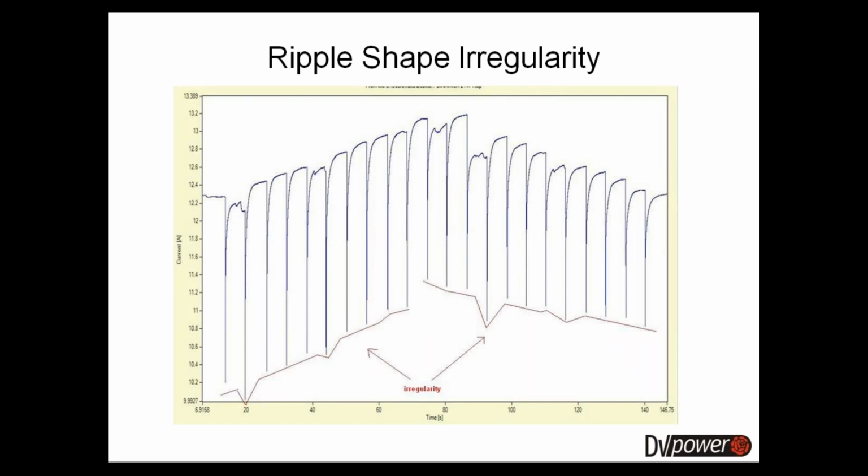However, when the tap changer has some sort of a problem, you can see that the ripples no longer have that smooth linearity. If we look at the same graph where the certain stationary contacts have problems, you can see that the ripples in those positions go much deeper.